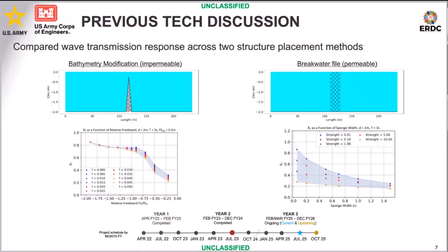And in practice, we have learned that, in theory and in practice, the dissipative sponge layer behaves the same as our bottom friction, our quadratic bottom friction, which we can put on the bottom. And it's more or less like acting on the full water column. Because this is a depth-averaged model, there's still a difference as to where the bottom friction is applied in those equations. So it's either affecting the full wave train, or just affecting the bottom boundary layer.